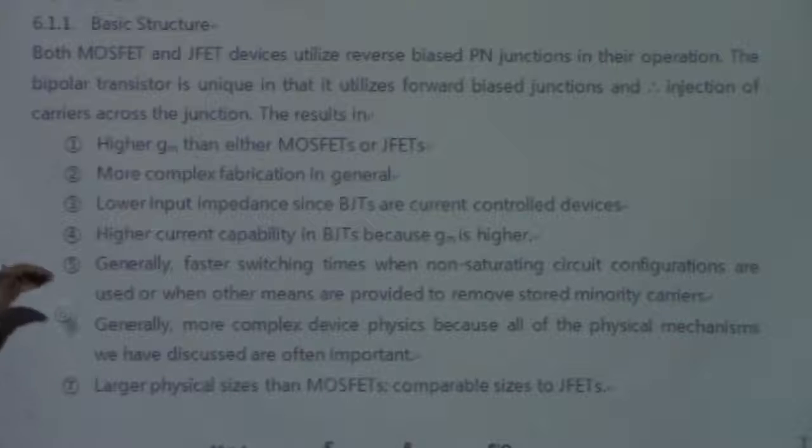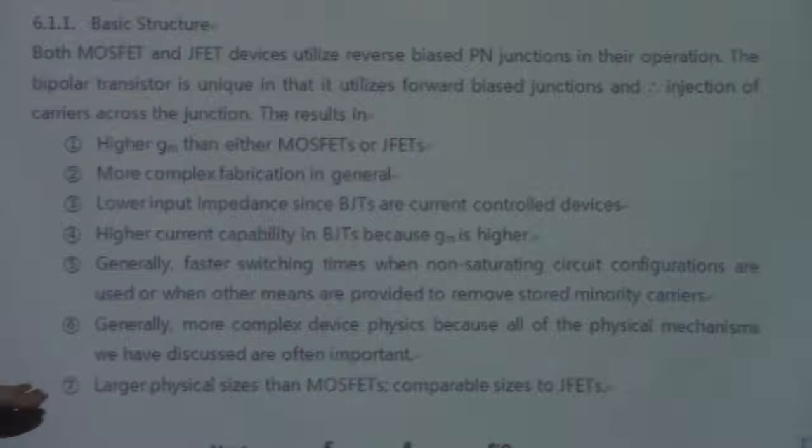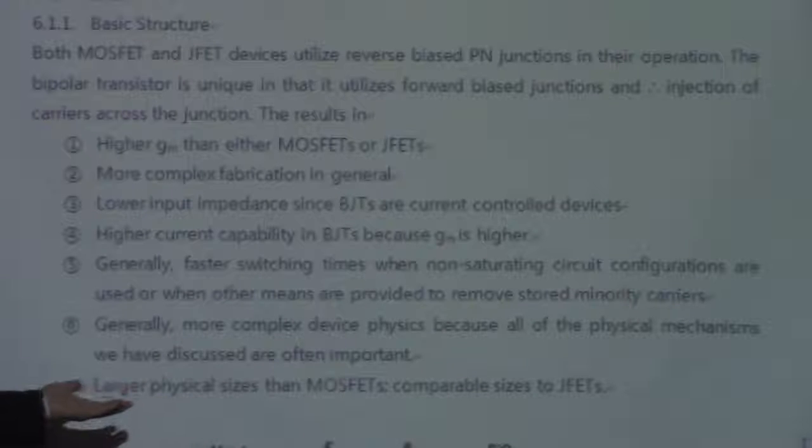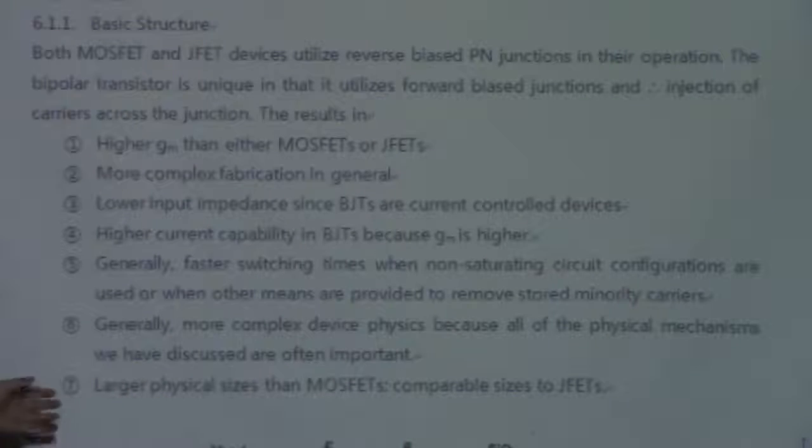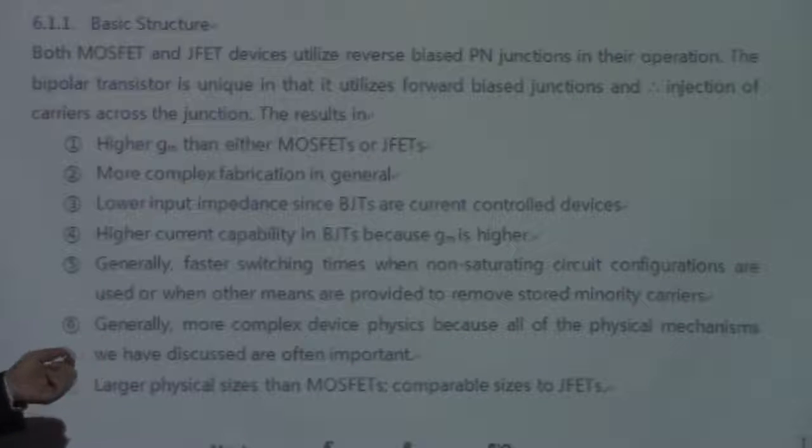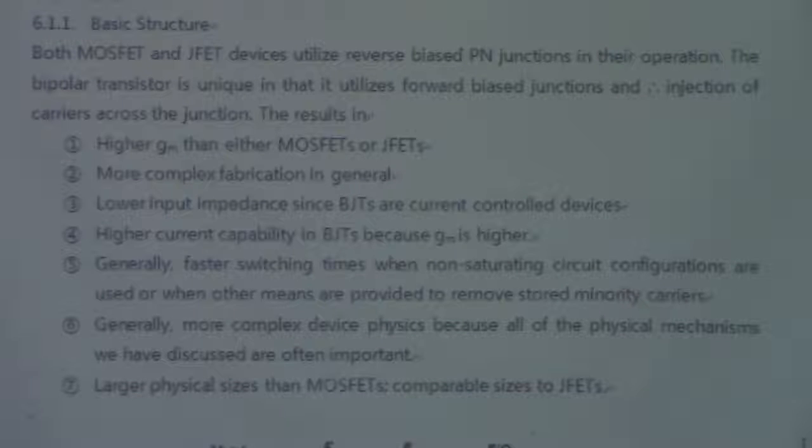So in modern VLSI or ULSI, nobody is using bipolar transistors for the integration. Most of the integration is done on MOS transistors because simply the bipolar is larger than the MOS transistor. How large? In a linear scale, it's about 7 times bigger. If you talk about the area, maybe it reaches 50 times or something.